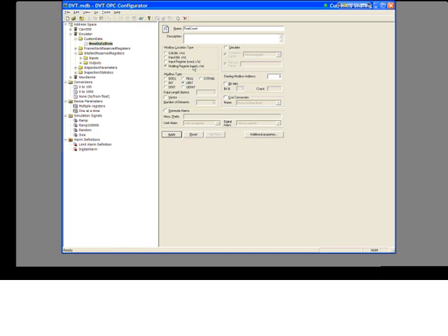Really, and this is Modbus lingo now, but our Modbus register space is a single unique register space. So the different Modbus types are not separated out. Generally, you want holding registers here. This is something that you generally don't need to change.